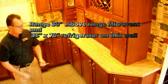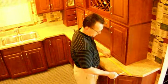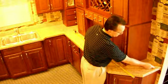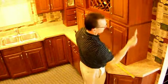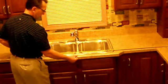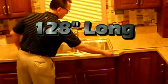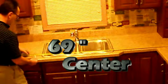This gives me an opportunity to measure the balance and realize that in that balance of space, I have to get a refrigerator and I also have to get a range. The refrigerator we'll be using today is going to be 36 inches wide, and we'll be using a typical 30-inch freestanding range. Now, I already know the center dimension of my window, so from right to left, I'll be going ahead and working off of that center.